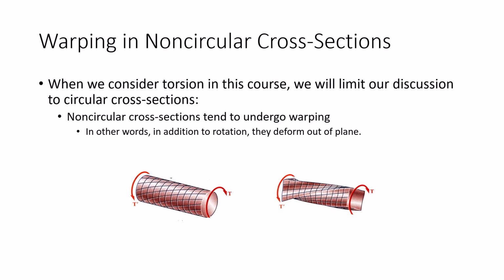If you have, let's say, wheels on either end of this square shaft and you twist it, the ends of the shaft are going to butt into the wheels. And that's not going to happen if the shaft is circular. Okay? So before we even get into the math, and this is largely for you mechanical engineers, if you have an engineering system and you've got something that's twisted, make it circular. Make it a circular cross-section. It's going to be a more efficient response, and it's going to be a more desirable response.